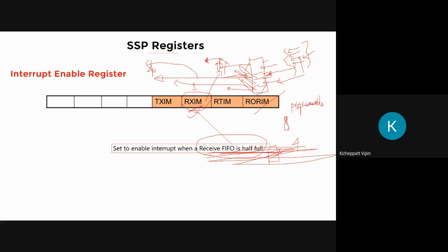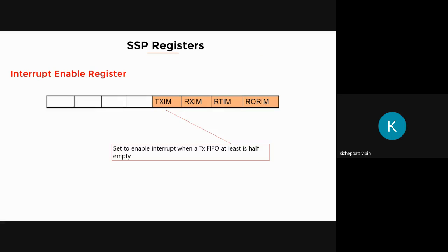Again, very important: when we are doing packet processing, everywhere we'll be putting FIFOs for buffering data. You don't want to go for an overkill or underkill. So when the FIFO or buffer is half full, you will start processing it, assuming your processing speed is good enough so that the FIFO won't overflow. But if you start processing much earlier, you won't be doing anything else, but just keep on checking this FIFO. Okay, anyway, I just mentioned everything.